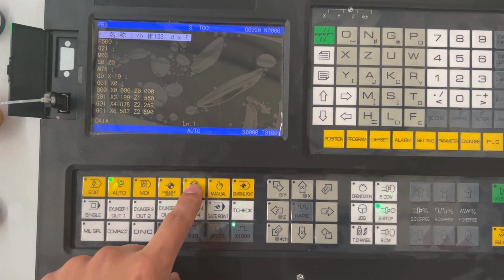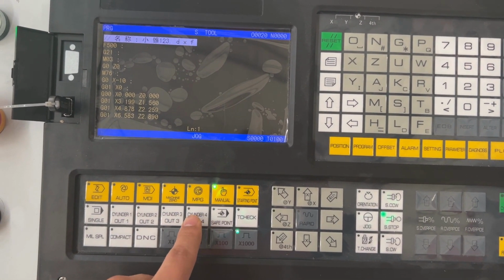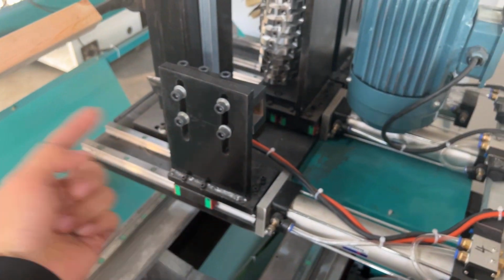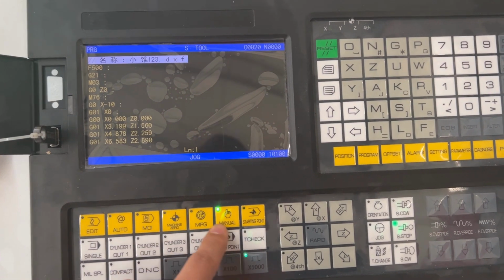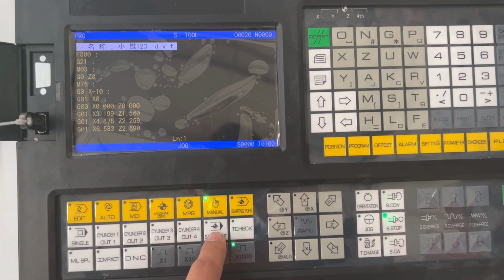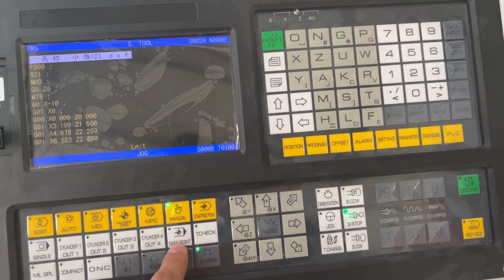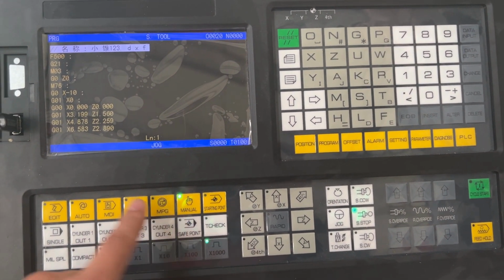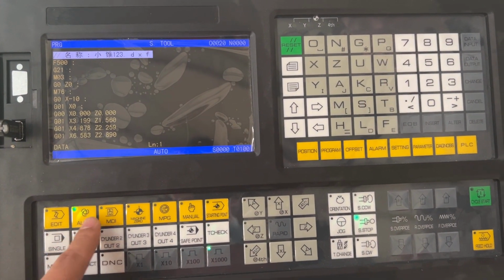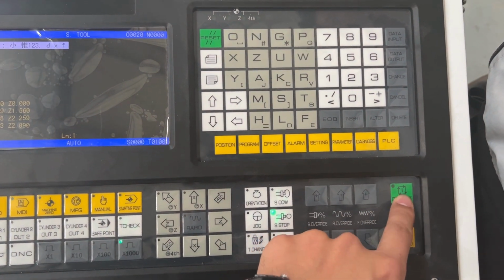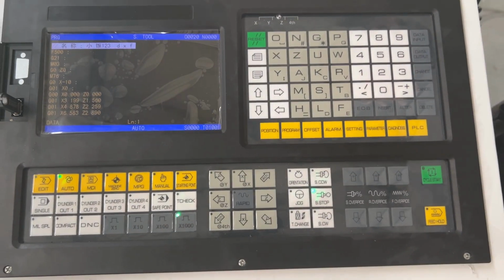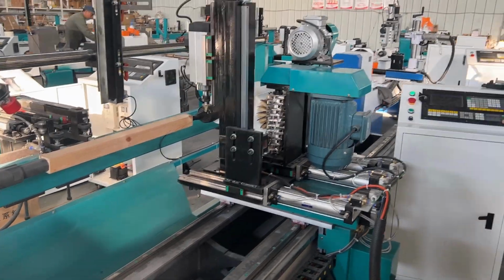Enable the manual function. Retract any ejected cylinders. Click Save Point. Return the machine to a safe stop. Enable the auto function. Click Cycle Start. Start turning.